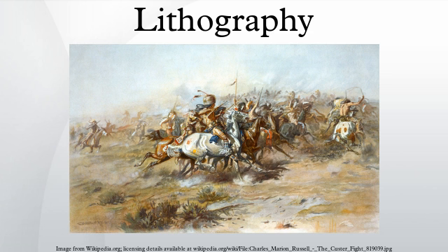Microlithography and nanolithography. Microlithography and nanolithography refer specifically to lithographic patterning methods capable of structuring material on a fine scale. Typically, features smaller than 10 micrometers are considered microlithographic, and features smaller than 100 nanometers are considered nanolithographic. Photolithography is one of these methods, often applied to semiconductor manufacturing of microchips. Photolithography is also commonly used for fabricating microelectromechanical systems devices.